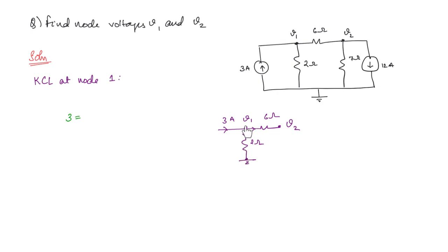What we do is express this current in terms of the voltage. Now the voltage, we should write V1 minus V2 or V2 minus V1. Whenever a resistor is given, if the current is flowing in this direction, then the polarity is taken to be positive here and negative here. This is the polarity that will be formed across the resistor.